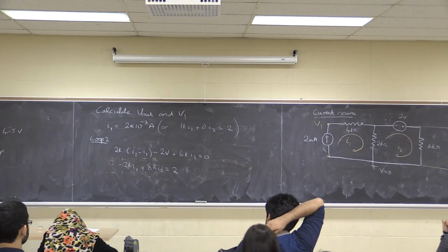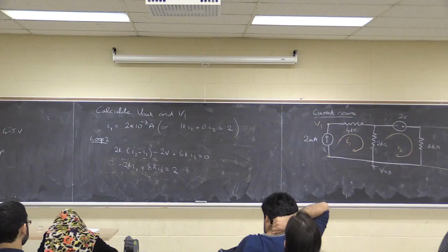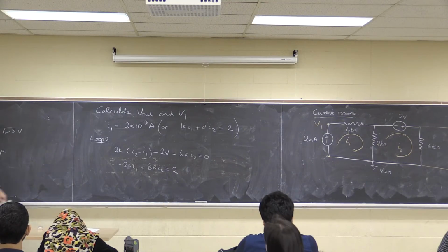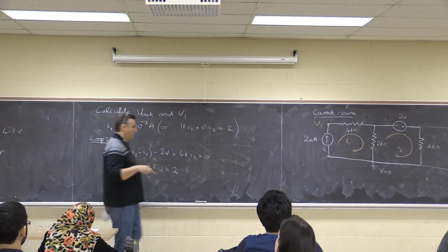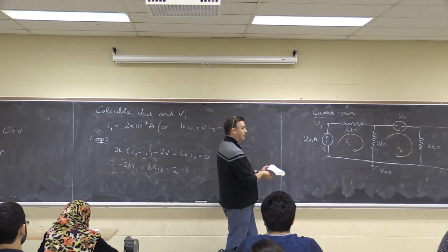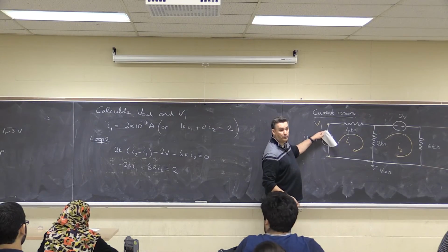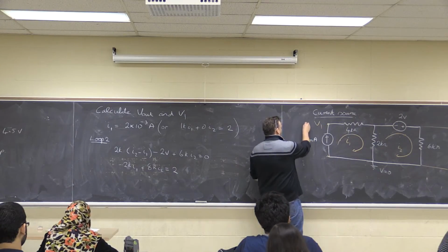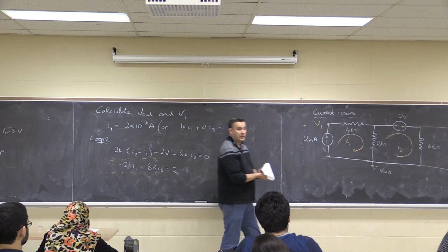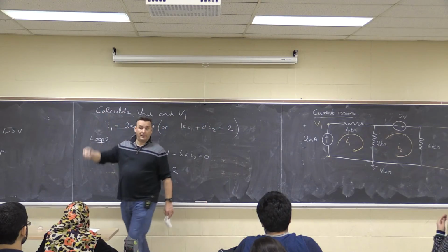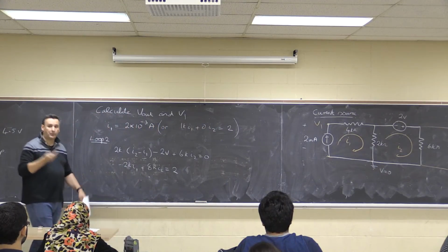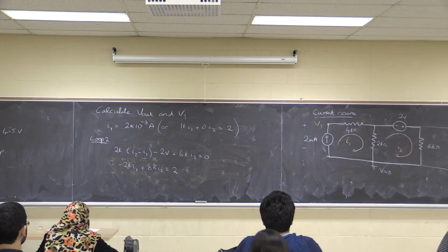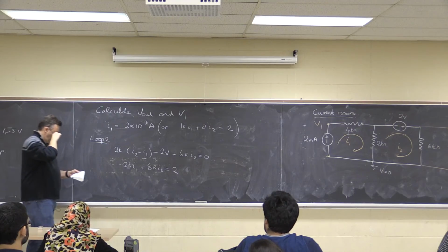So if I start, I'll call it negative V1 because I know it's a voltage increase because of the direction of the current. Current flows out of the top positive and into the bottom, so if the current is flowing this way, the voltage must be plus-minus like this. If I go round a loop and I go in at the bottom through the negative terminal, I call that negative voltage, and then all the other voltages will be positive.